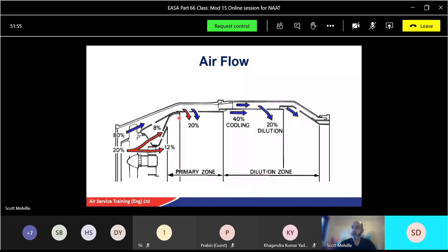You've got your inner layer and your outer layer. So between these two layers, you'll have 80% of that 100% we'll use for cooling air. The other 20% will help aid combustion. Okay, so basically the overall mixture is 20% for combustion, and we'll use 80% for cooling. And that's represented here by in between the skin.